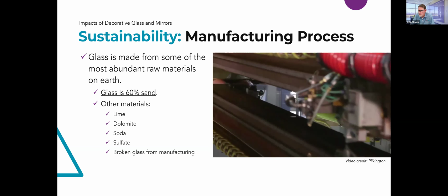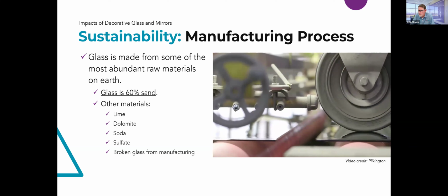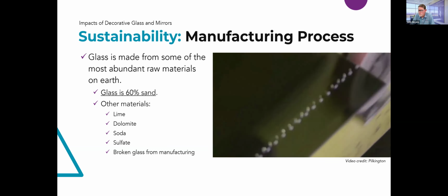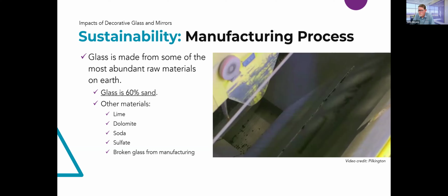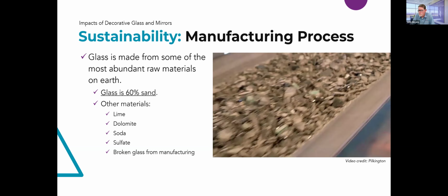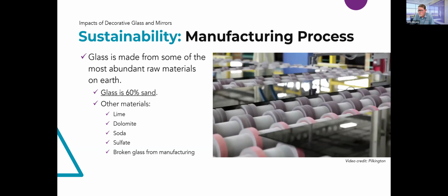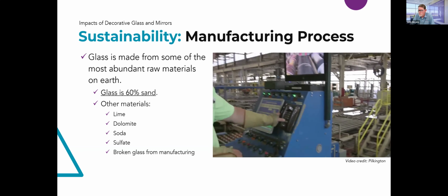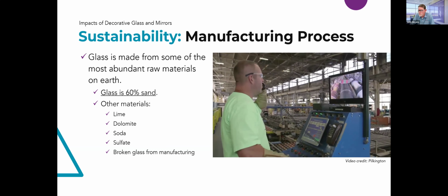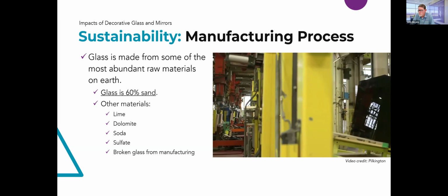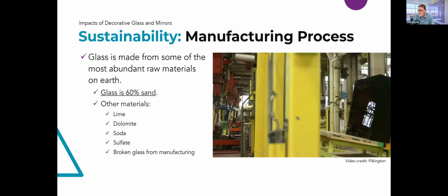Now the glass is scored, so it can be snapped to predetermined sizes. Indentations left by the top rollers are removed on conveyors and sent to be reintroduced as cullet at the beginning of the melting process. After passing through the automatic handling stages, customers' orders, which might involve a range of thicknesses and sizes, as well as special coatings, are packaged for delivery.